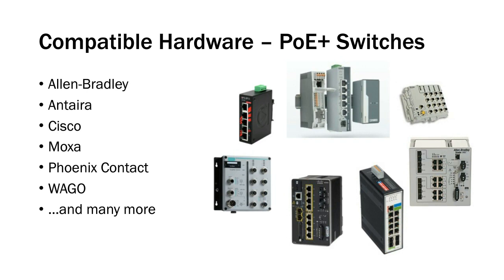And of these names up here, I know Phoenix Contact actually makes a line of DIN rail mount injectors in addition to their switches. If anybody from any of these companies is on the line, I apologize if I don't know your product line well enough. I'm sure some of these other companies make injectors as well, but it's really easy to find them. You just want to make sure you're looking for PoE plus or Type 2 802.3at, and then that'll give you what you need.